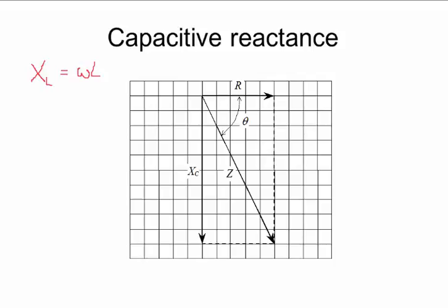But if you make it an impedance, in other words, this changes to a Z, then this means you now have the complex operator combined with this. Now, the same thing happens with capacitance, but everything is divided by 1. So you've got this 1 over j omega C, like that. The thing is, we don't like j's in the denominators.